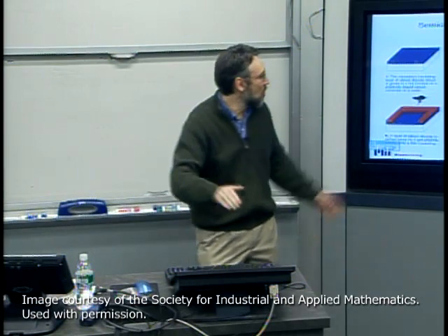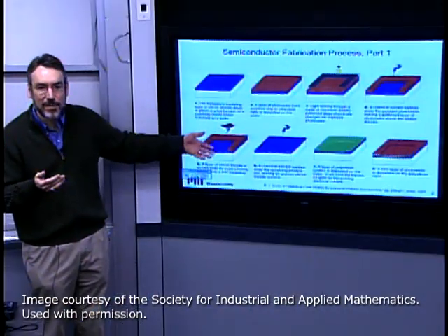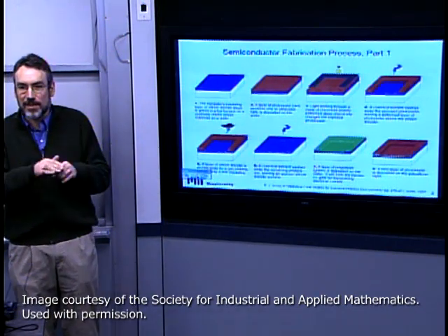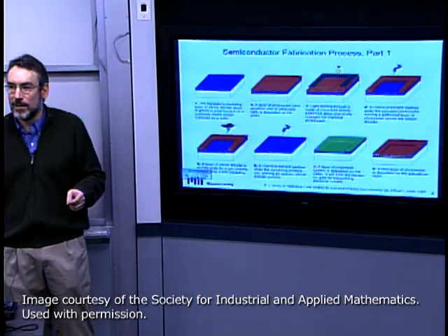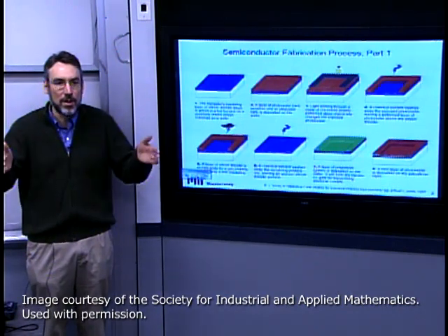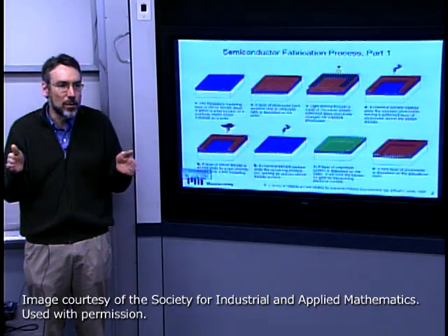Now everybody knows exactly where they are across every place in the wafer. One can even over-etch a little bit, right? You don't even have to try to set up a timed etch. If I was etching at 1,000 angstroms a minute and I started with 5,000 angstroms, I might etch for 5 minutes. But to be sure that I've got the same degree of uniformity everywhere, I might etch for an extra 10 seconds. That way I'm sure that I'm clearing everywhere across the wafer, even if there's spatial non-uniformity in my etch, or today's etch is etching slightly slower than yesterday's.